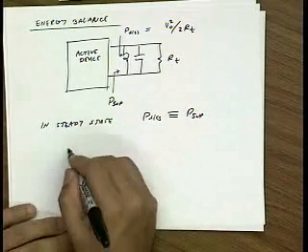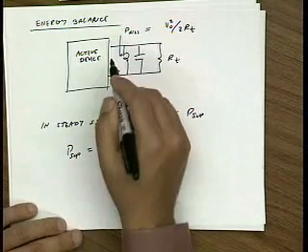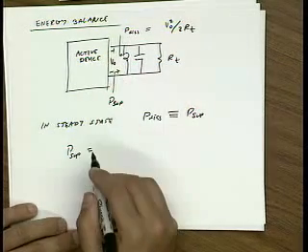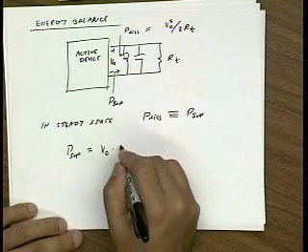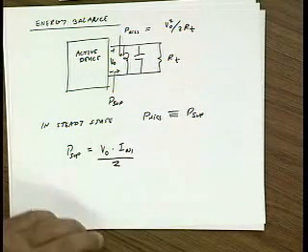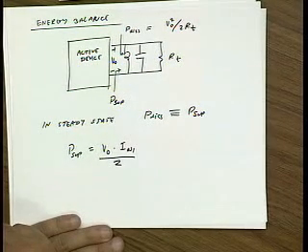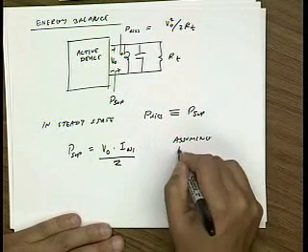So what's the power that's being supplied by the circuit? Since this voltage across here is VO, if I knew the first harmonic current, I omega 1, coming out, this would be the power being supplied. So here I'm assuming a high Q tank.